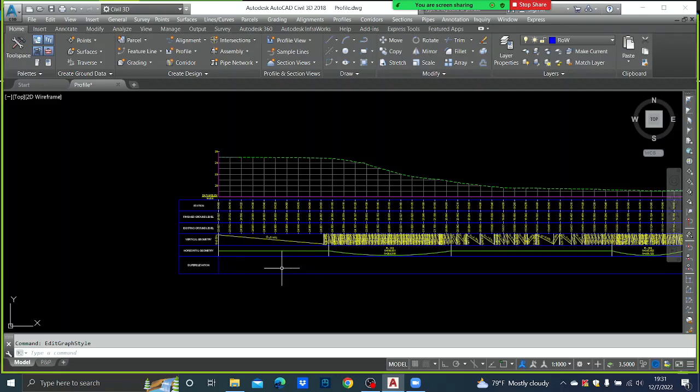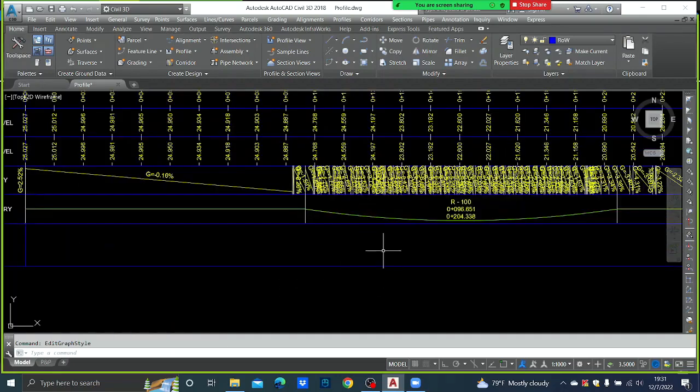In this band you have to give the super elevation, right? Now guys, there is one thing I have to tell you. In Civil 3D, there is an option called automatic super elevation development. Never use that. Okay, this is kind of a bug. Why? Because when the Autodesk people are coming, also we are telling why we go. No, it is not a bug at all.